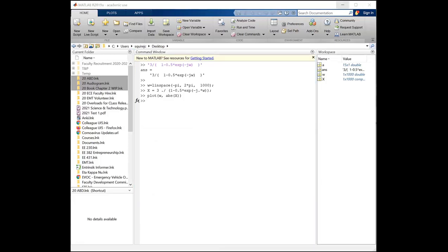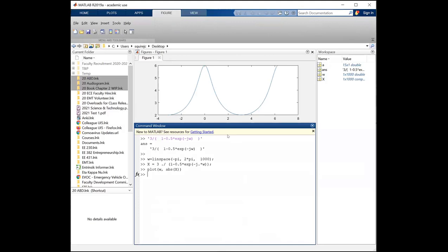And let me show you what that looks like. So that's what it looks like in the frequency domain. So sure enough, between 0 and pi, it's unique. You can see it has a lot of low frequency energy. And that makes sense because remember, our time domain waveform didn't oscillate up and down. It just simply decayed away. So it's got some low frequency energy, no high frequency energy. And then you can see how it's symmetric around pi, going up, and symmetric around 0 on the left-hand side. If you wanted to graph its angle, you could do that.